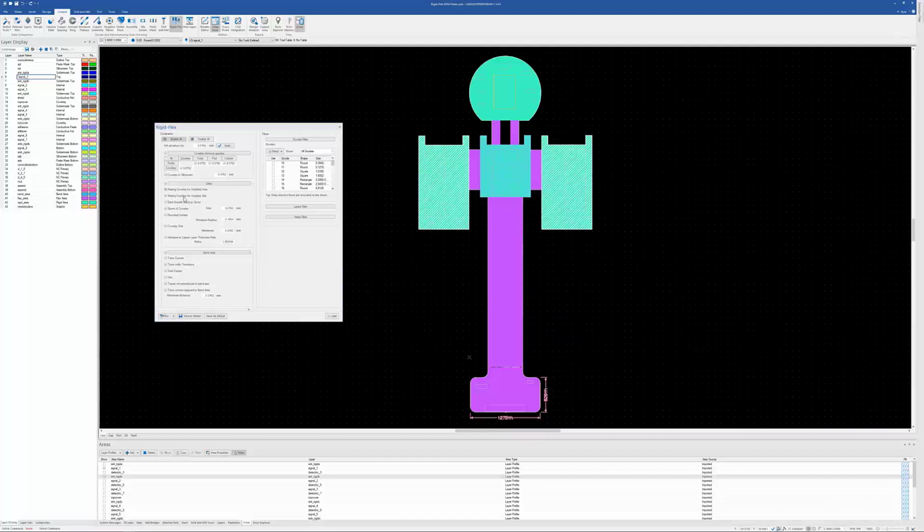So, missing coverlays for various types of elements, slivers of coverlays or data outside the stack-up zones, things I was talking about earlier, looking for either rounded corners for items to make sure that they're rounded or not in some cases, trace corners, make sure we don't have those in bend areas.